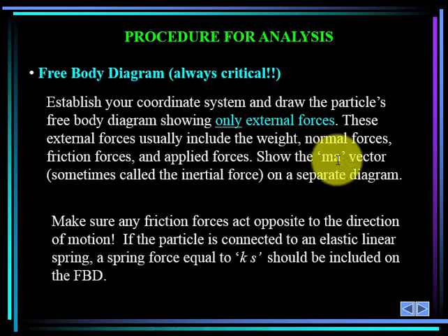And we will show the ma vector, or the inertial force, on a separate diagram called the kinetic diagram. Be very careful with friction, because friction always opposes an attempt of the body to move.